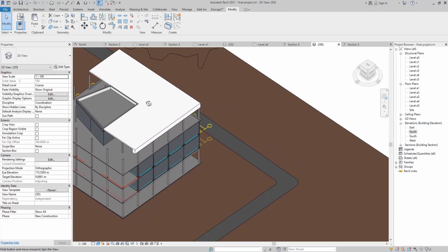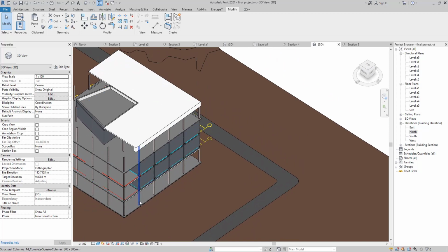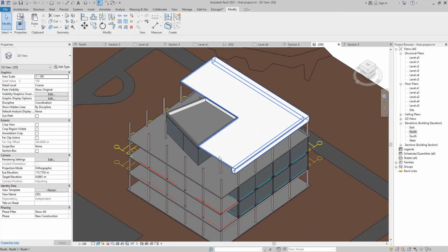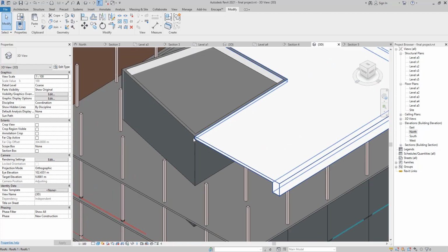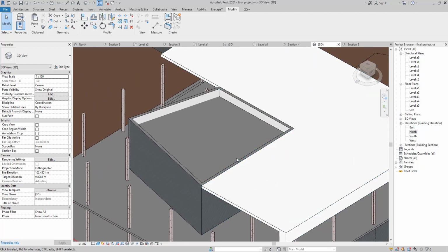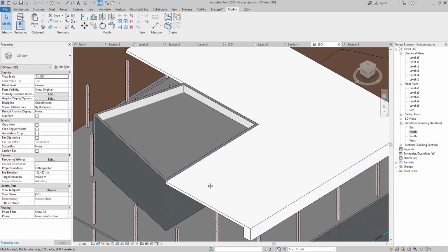First, as you know, we designed our roof element by using Sweep in model in place. We do not have access to change the shape in the two horizontal dimensions, because we designed one horizontal shape here, and after that we give the line or direction from this point to this point, so that the sweep creates this horizontal shape in this direction.